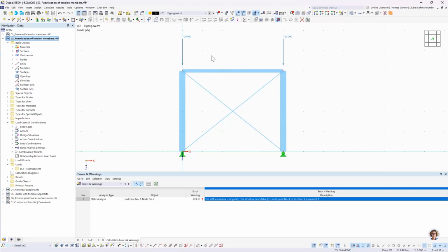And for the next iteration, where it is deformed a bit, we won't have these members anymore. That means with this deformed system, the next iteration would move it, and the next iteration would move it again. The program won't be able to find an equilibrium for the system anymore, since it's just not stable.